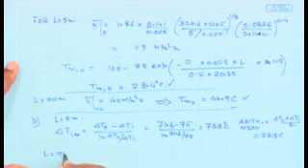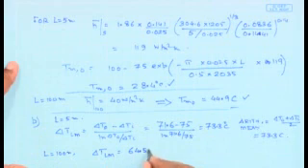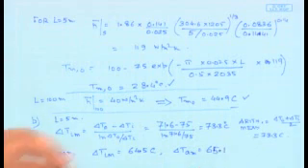When we do this for 100 meters, you calculate this and see that delta T LM is equal to 64.5 C, and delta T arithmetic mean comes out to be 65.1. So for this specific fluid at two different lengths of the pipe, we see almost no difference for shorter length of the pipe, and the differences will start to creep in as the length of the pipe is increased, but still it's not going to be noteworthy.